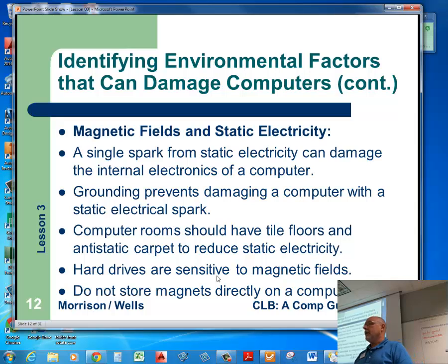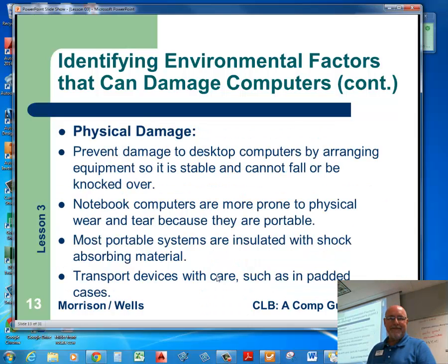If you have carpet, like at your house, and you have a desktop computer in particular, and you're using it in one spot where there is carpet, then you want an anti-static mat, or you want some anti-static spray. Usually not a problem in Kentucky. We have plenty of humidity. Static is usually not an issue except for in the middle of the winter.